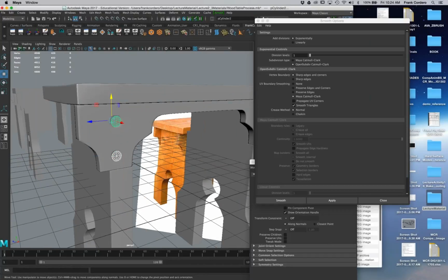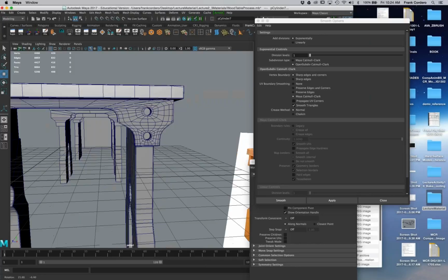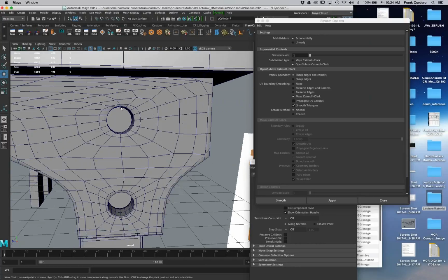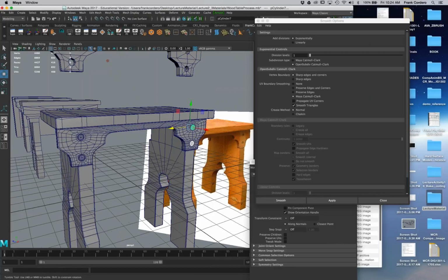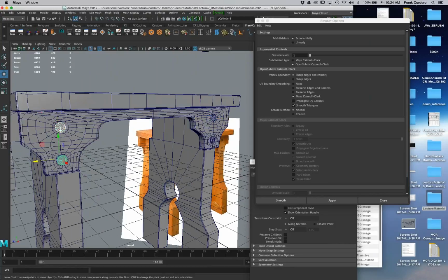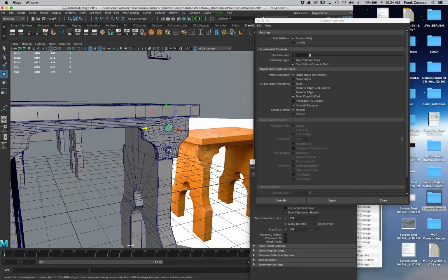And then let's go over here, Command duplicate them. And now I'm going to go ahead and turn on my wireframe so I can see where I'm snapping. I'm going to use the middle vert here as a guide. There we go. And now I start grouping things. And now I start kind of getting the benefits of grouping.